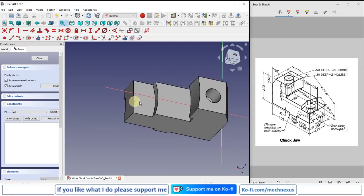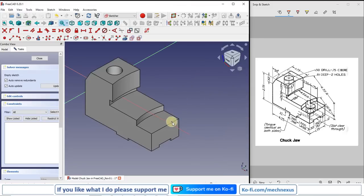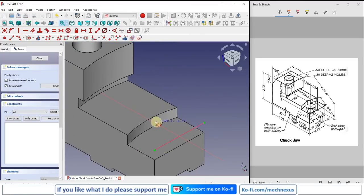So I will project this edge here, and I will draw a circle on this axis, and I will give it diameter of 0.5. I will give 0.5, and here it is 0.75.